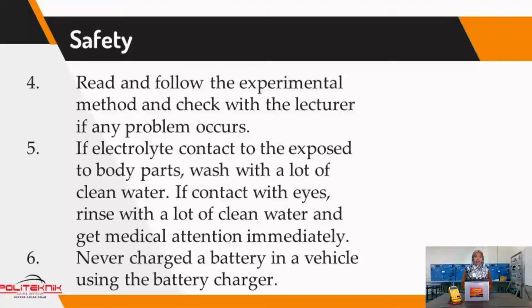Fifth, if electrolyte contacts exposed body parts, wash with a lot of clean water. If contact with eyes, rinse with a lot of clean water and get medical attention immediately. Sixth, never charge a battery in a vehicle using the battery charger.